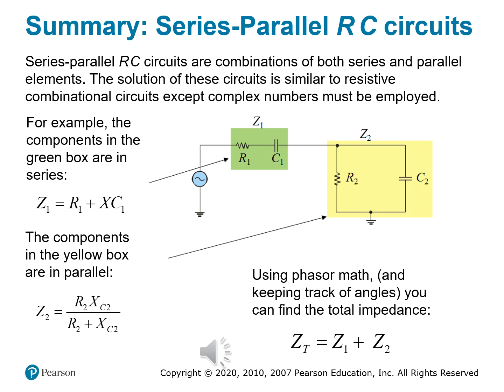Let's just go ahead and review what you're expected to bring into the problem. You have reactance for capacitors, again the formula you should know by now: XC equals 1 divided by 2 pi f C. You have complex impedance handling from rectangular to polar form. Then you have phasor addition rules: real plus real, imaginary plus imaginary. Remember, likes to likes. You're going to use all of these tools to navigate this maze.